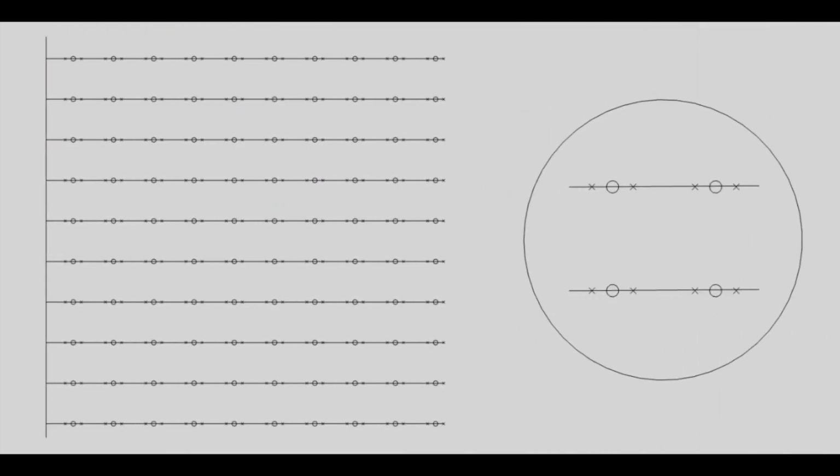This is the layout that we're going to work with today. You can see that it's a block of trees and sprinklers. The trees are circles and the sprinklers are either side of those trees. The tree spacing is 50 feet, but the sprinklers are 10 feet either side of the tree. So it's a good example of non-uniform spacing along the lateral pipe.